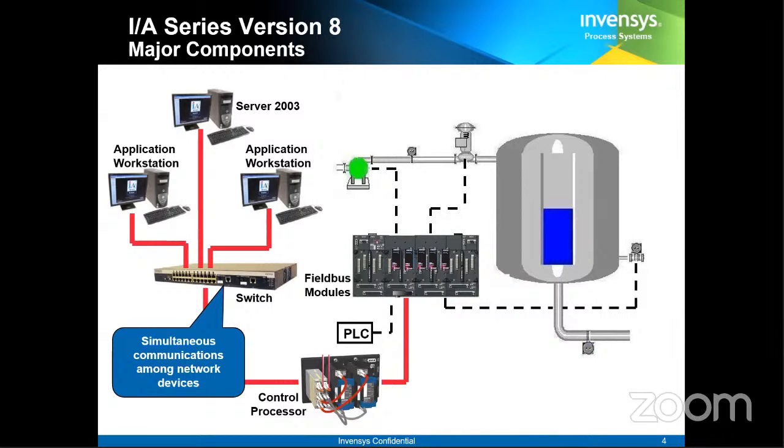In any case, if one control processor fails, the complete control will immediately switch over to the secondary control, so that you will not have any loss of communication on the field side, nor on the control room side. You will not feel any glitch.